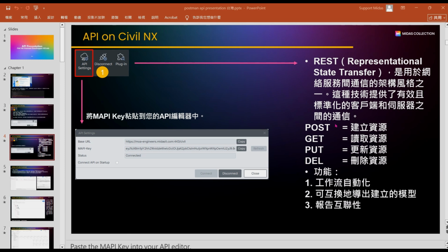So yeah. So post is creating something out of nothing, and put is replacing something from another thing. And delete is just delete. So keep in mind that if you are choosing delete, it means that if you have many section properties, maybe 10 or 15, and you want to delete the section properties, you can use delete. But if you want to delete only some of the section properties, you cannot delete some of it. So this delete command will delete all of them. Okay.